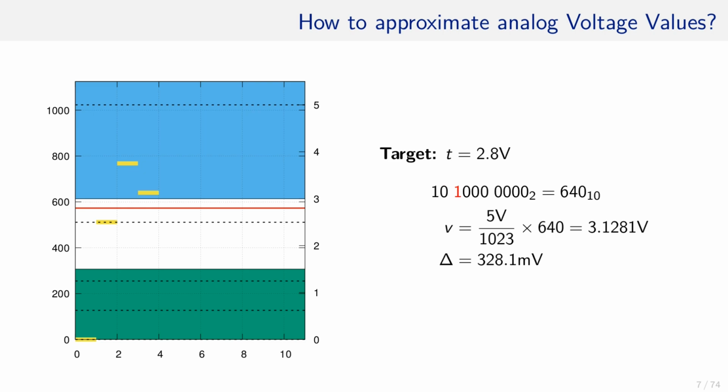If that third MSB is set, the value is still too high, so this bit is not set either. Still too high, but we are getting closer. Okay, that is too low. Therefore, we keep the current bit. We are only halfway done. Let's continue with the next bit. And this one.